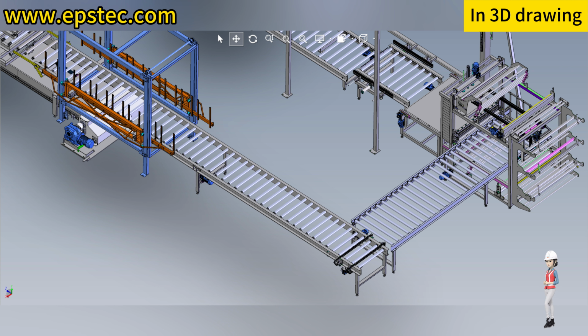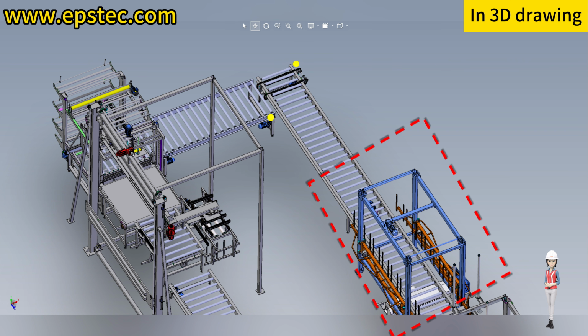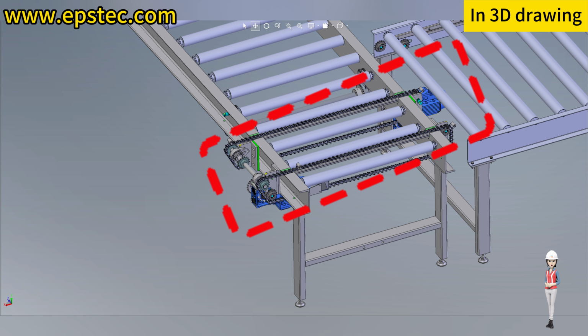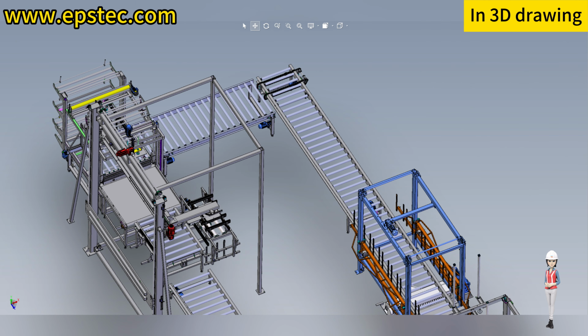During the push process, there are two options for manual operation. If the worker is unable to remove the excess remaining boards from the up layer in time, the worker can press the pause button. At this time, the stacker conveyor and push plate will stop, allowing the worker to have more operation time. If the worker can remove the up remaining boards quickly enough and have enough time, they can skip this pause step.